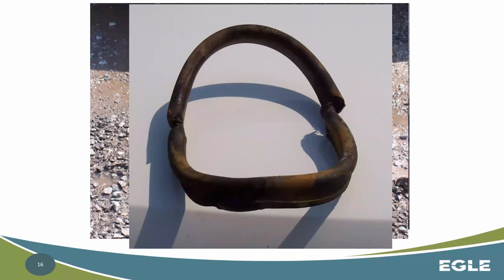So that obstruction could have likely been removed and identified well ahead of time had this hydrant been normally and routinely maintained and the water main flushed often. Maybe not, maybe it was stuck in such a way that it just so happened to finally break free and come into that scenario during that fire session or that firefighting session. But more than likely, it just had not been fully flushed for a long enough period of time to allow that gasket to find its way in there.